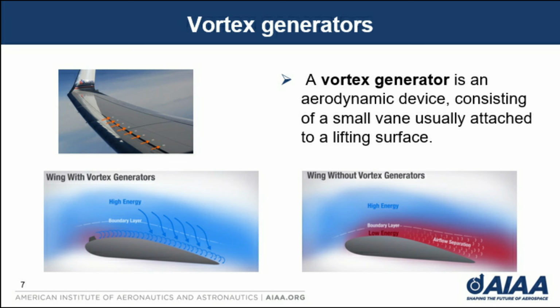The results are shown by comparing the profiles with vortex and without vortex generators, and also comparing different AOA. At low AOA, it is obtained that the drag coefficient increases rapidly and the presence of the vortex induces a modification of the movement of the detachment point of the flow, and their oscillations are inhibited.